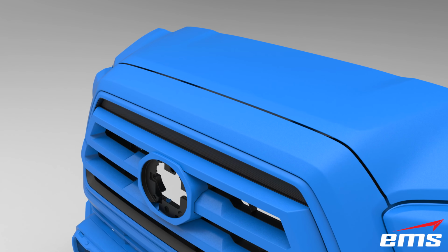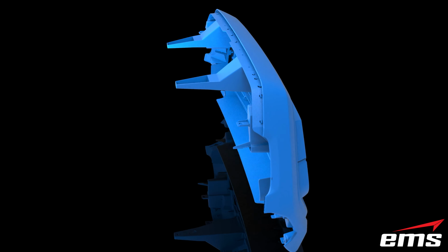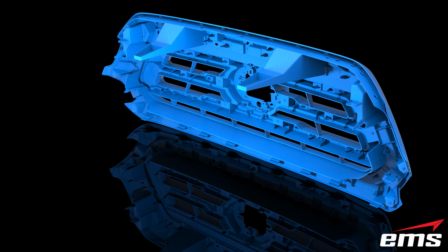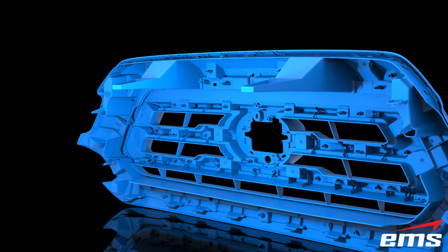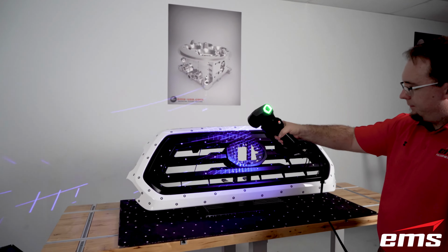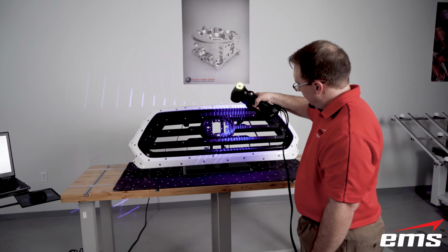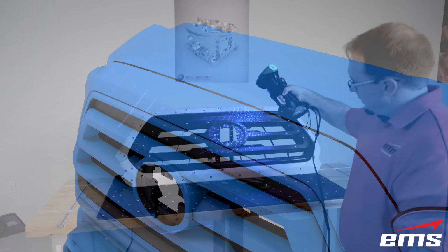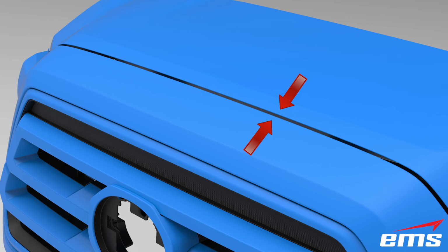Now, one key thing though is we do need to hold the part in the correct position, in the assembled position, because the part is plastic, it's thin, it's actually an assembly of plastic parts, so you would still need a simple holding fixture to hold the part in the correct position. But from there, we can just 3D scan the part and then do the flush and gap check virtually to the panels around it, because we have all of this stuff in 3D CAD.